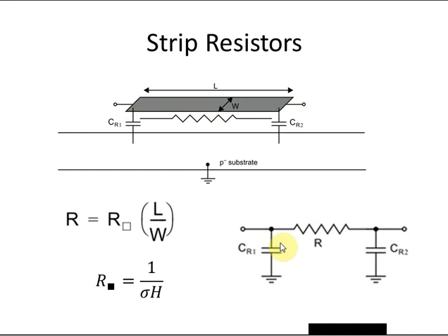So there are some other details here about contacting the resistors that are not being touched on here, but in general you're going to want to consider all of the interconnect that's involved going to and from this strip. That can all be considered as part of the resistor, if you really need to be that accurate in terms of the value of the resistance.